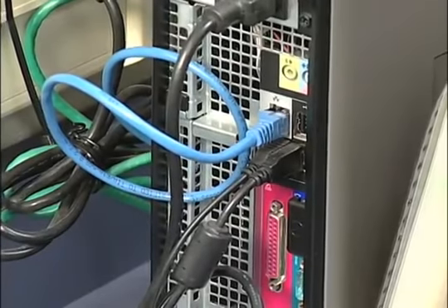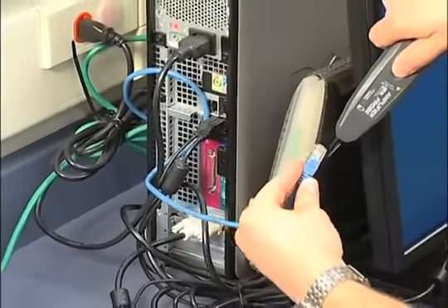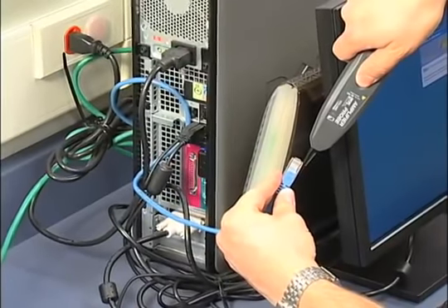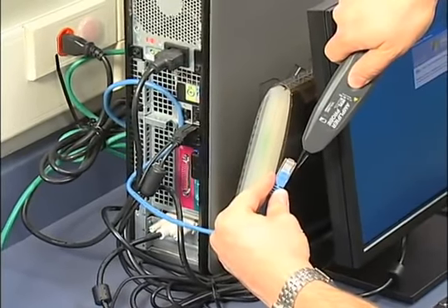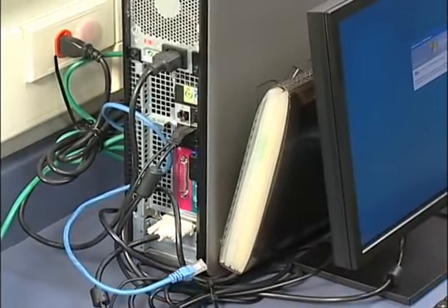There are two modes available for cable tracing. An audible tone generator works with any inductive amplifier probe, or you can use the port blink function to identify the port with the switch link LED when connected to an active Ethernet line.